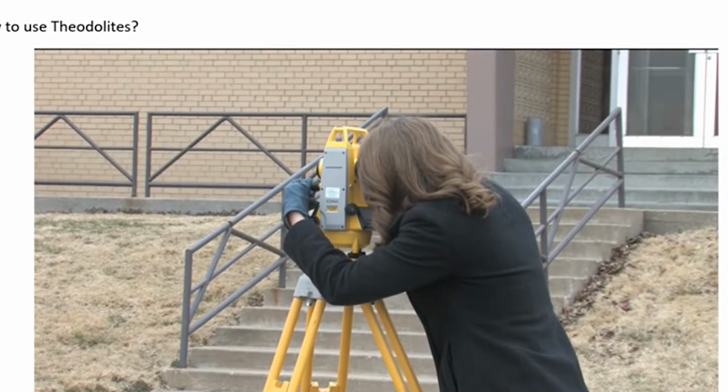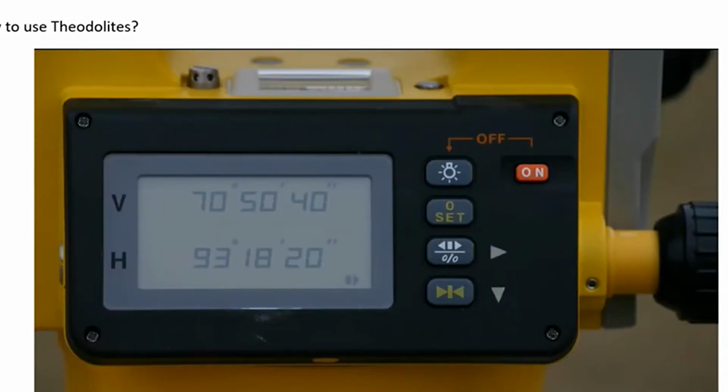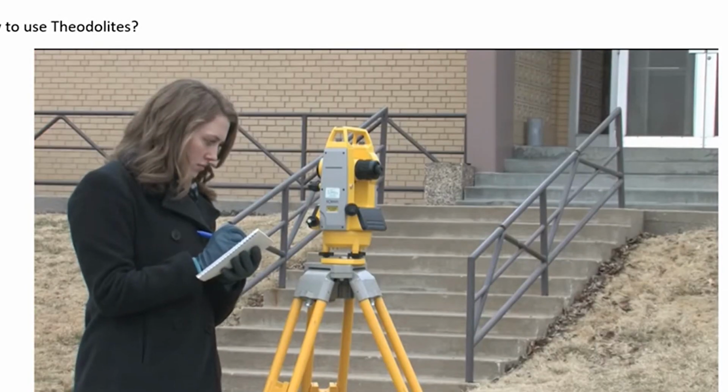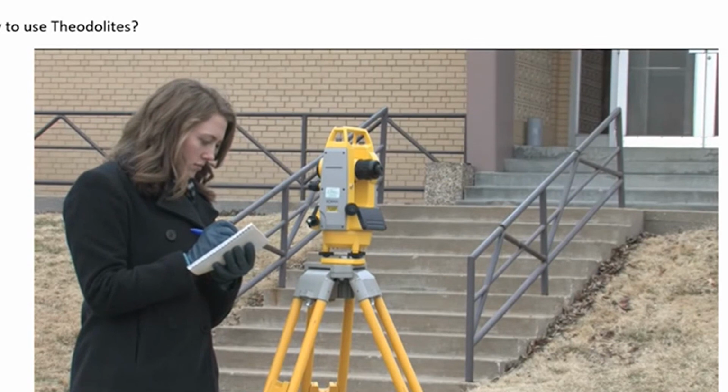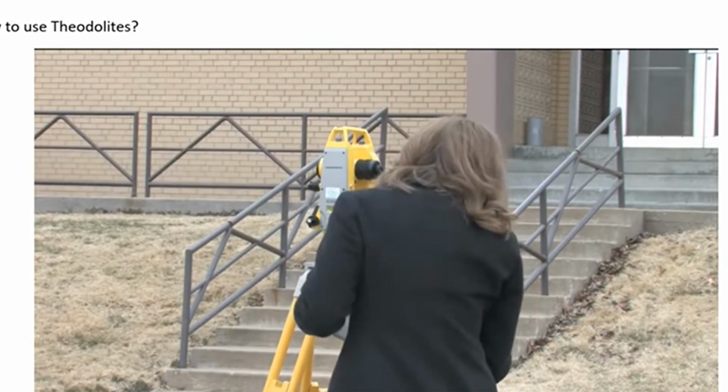Once the instrument is fully sighted in on the HI, the vertical angle reported should be approximately the same as before. Proceed to lock the instrument and record the horizontal, vertical angles, as well as the upper and lower stadia readings at point B. Remember, this is a plunged horizontal angle.